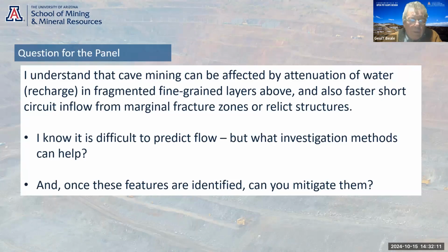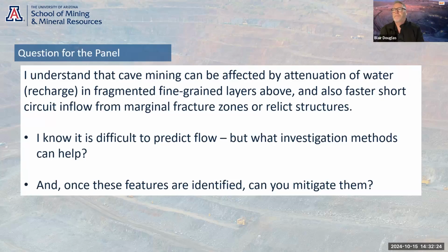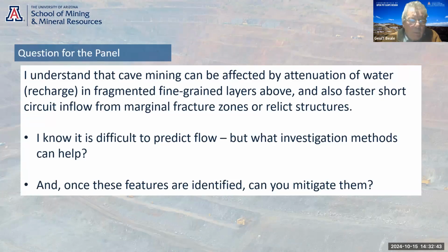So if you have, let's say, a crater zone with an accumulation of water in the bottom of the crater, then the inflows you see underground are often directly below the middle of the crater. And there's another example in Canada that we'll work on, where the main source of inflow to the cave zone is water along two paleo channels, and all the wet panels and all the wet draw points are directly below where those paleo channels enter the cave zone.